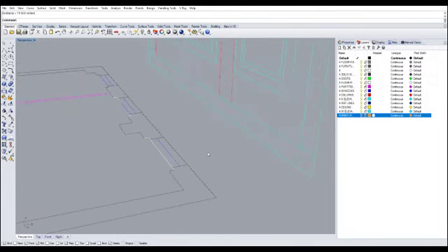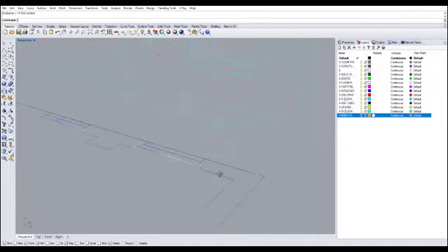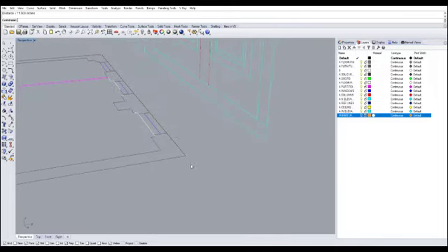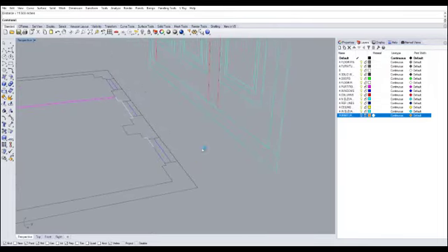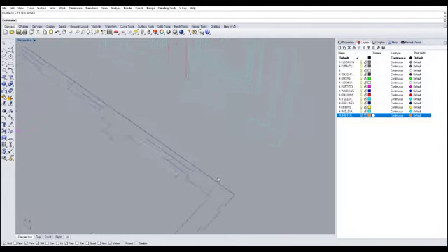Extrude converts a closed two-dimensional shape, including circles, blocks or rectangles, into 3D by extruding its line work into three-dimensional space, or simply the z-axis.